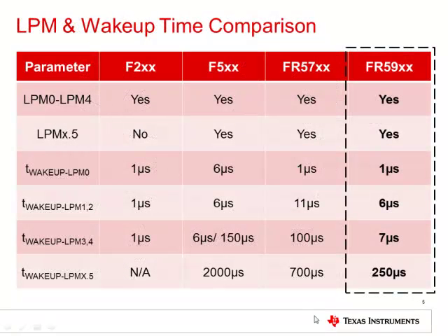This slide provides a quick overview comparison of wake-up times for various low-power modes across different 430 families. Applications require different active duty cycles depending on the functions they are executing. In cases where the active duty cycle is high or the device needs to respond to events on a highly frequent basis, a shorter wake-up time is preferred. As an example, the CPU may be turned off and the device placed in LPM0 while waiting for a high-frequency UART data byte to be received.